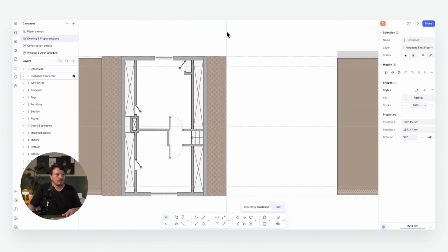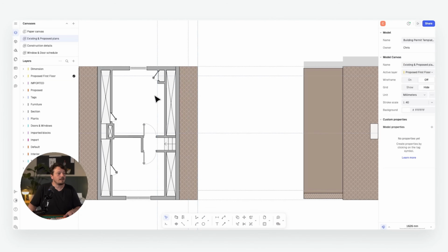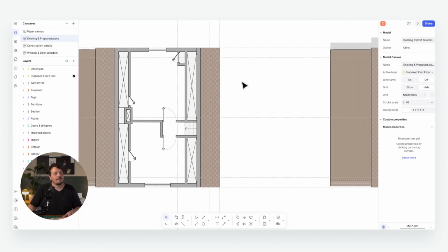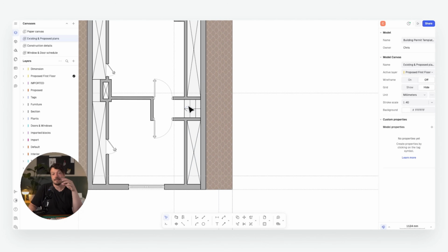So again, we want to bring the face of the dormer in by 600mm, and we want to align the new face of the bathroom wall to this existing wall. So that's the space we have to play around with. And then the next step is to try and think about the 2 dormers that we're going to be creating. They want to be symmetrical within that side elevation. So the one restricting factor you'll notice is the stairs. So the stairs are staying. And the position of the stairs isn't central within the space.